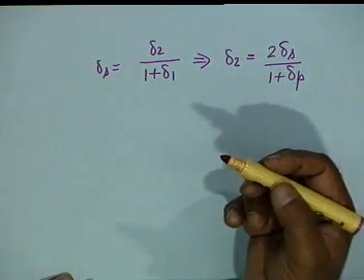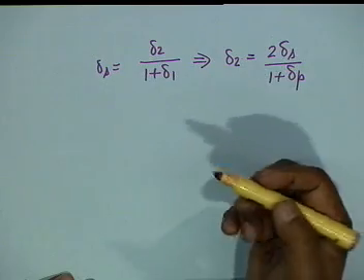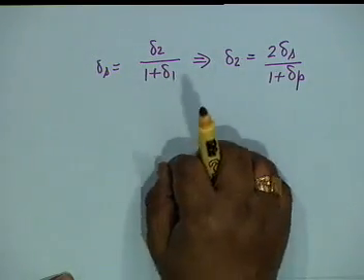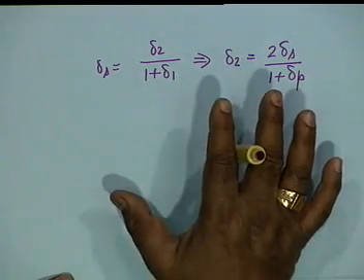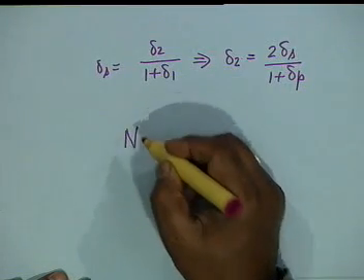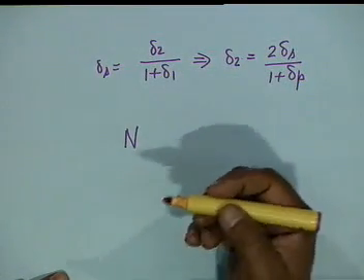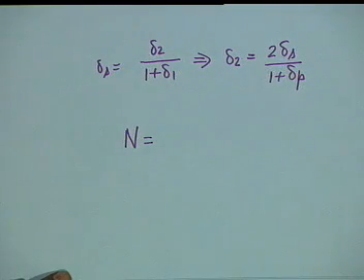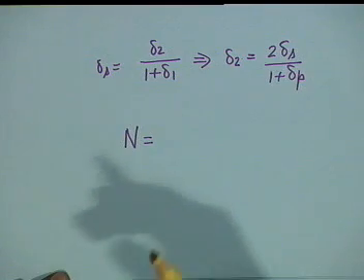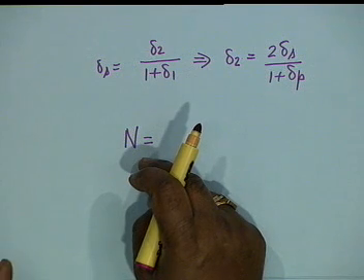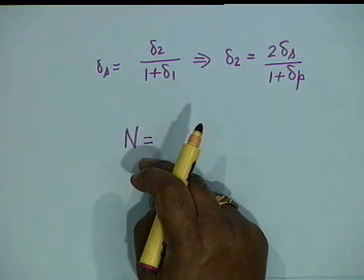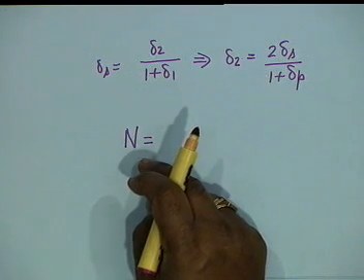And then the only formula available for estimating the order, unlike IIR design where NB and NC are given by analytical formulas, and you have to choose the integer higher than whatever value comes. Here only an estimate is available. There are complicated formulas. There is no point in using them, because after all you shall have to iterate a number of times. If the number that comes here does not suffice, then you have to increment it by 1. Then if that does not suffice, increment it by 1 more, and so on.